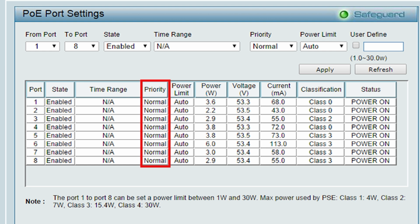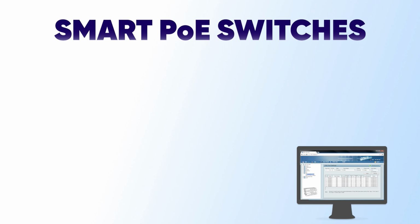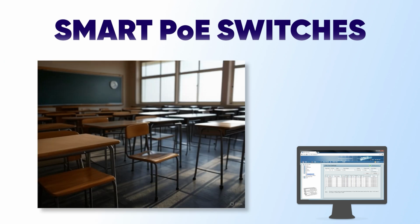The admin can also configure specific PoE time profiles, which enable and disable the PoE power on a per-port basis according to a specific schedule. This may be useful in a school classroom application with a requirement to shut down wireless networks during non-school hours.